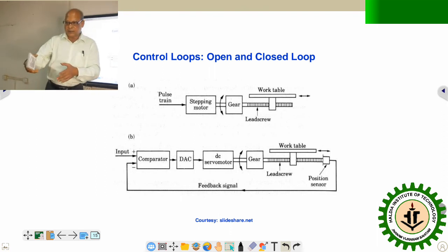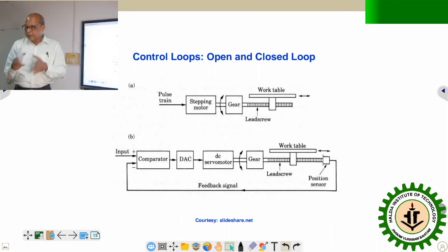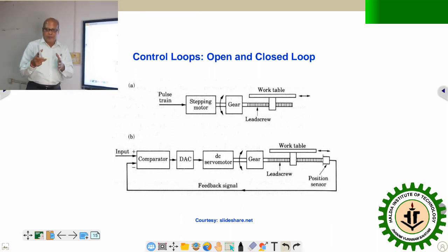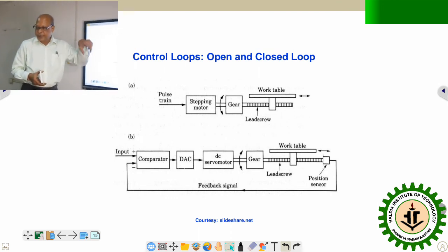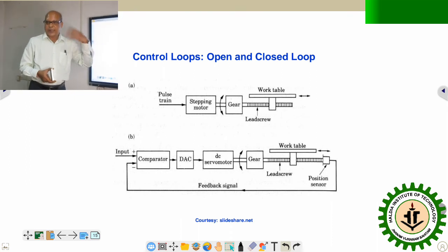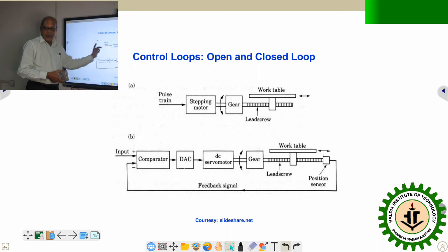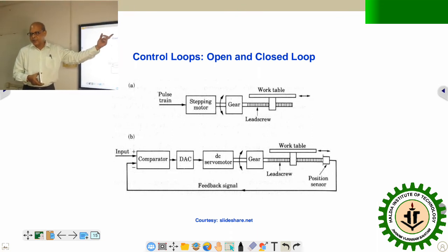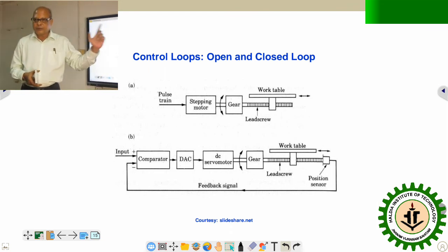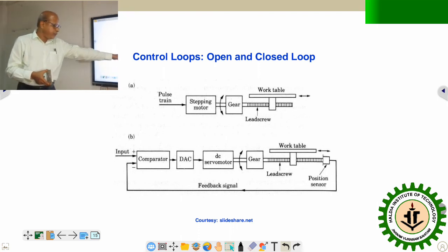So in the example that I had given you, 50 minus 1, this comparison equals 49, 50 minus 2, 48. So this comparison means 48 millimeter is still to go to reach your destination. This calculation will be continuously taken care of and implemented in the closed loop control system, so that eventually you reach your target destination with the desired velocity. It is a simplified form.